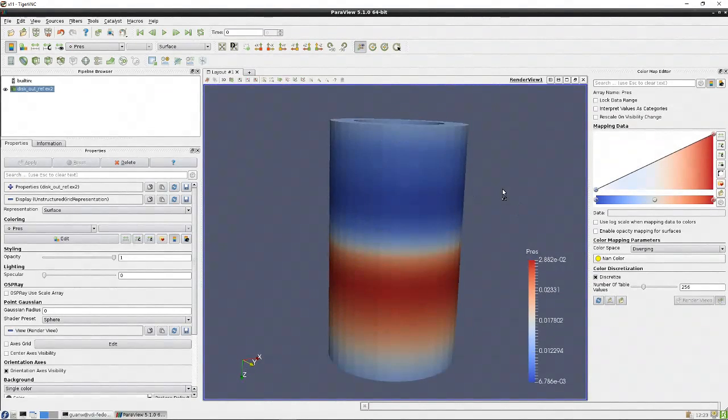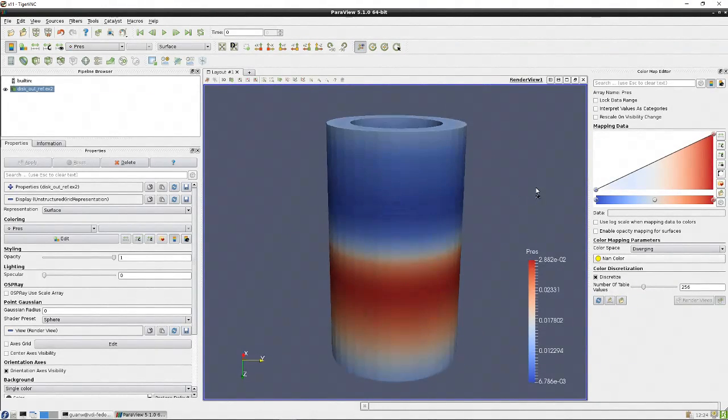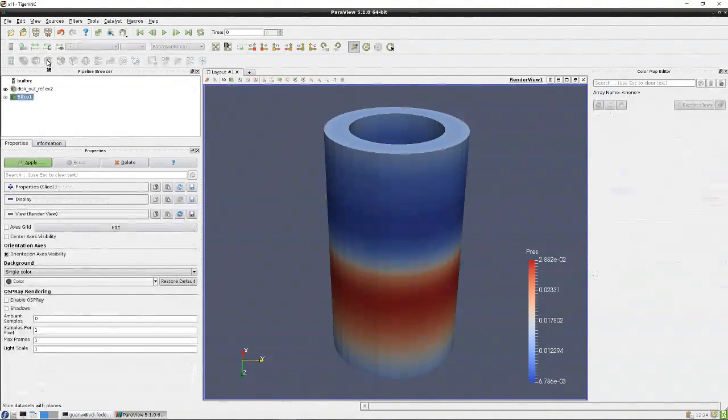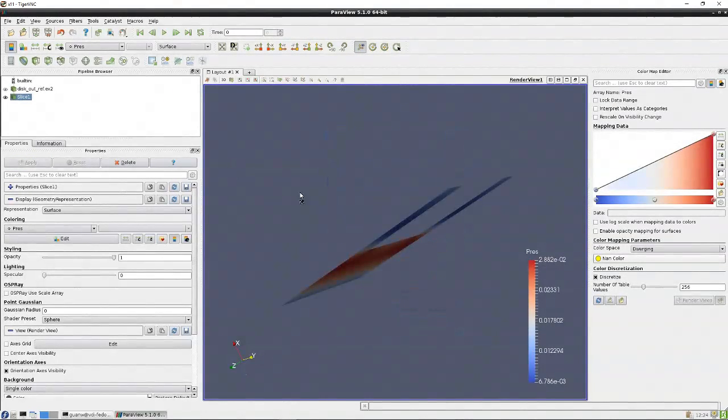Okay, you can see the pressure gets higher here and lower there. Okay, so that's the distribution, but you don't see inside. What's the inside? Certainly, you can choose some filters, like I click a filter like slice. I slice through, okay? I apply. So here's my slice, okay?